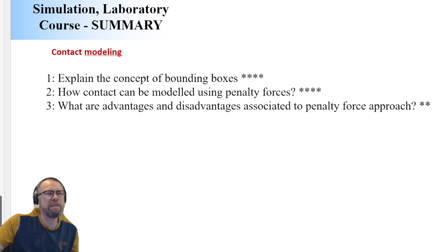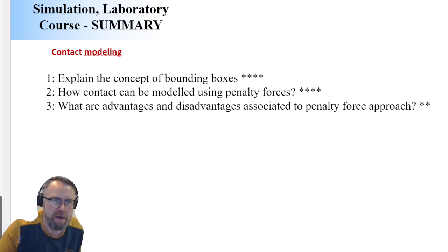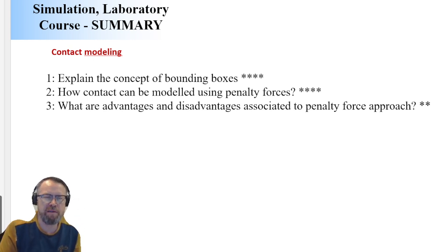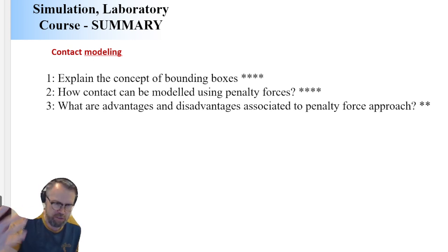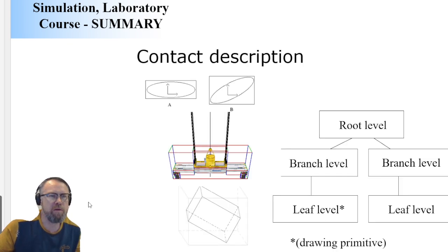Model reduction, so we discussed this already. Contact modeling, explain the concept of bounding boxes. This is the contact prediction procedure and how contact can be modeled using penalty forces, which is based on the penetration indentation. What are the advantages and disadvantages associated to penalty force approach? It's straightforward to use, but it's sensitive to integration settings, in short. All right, so